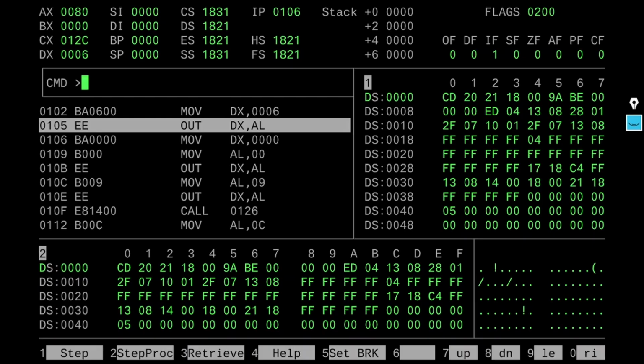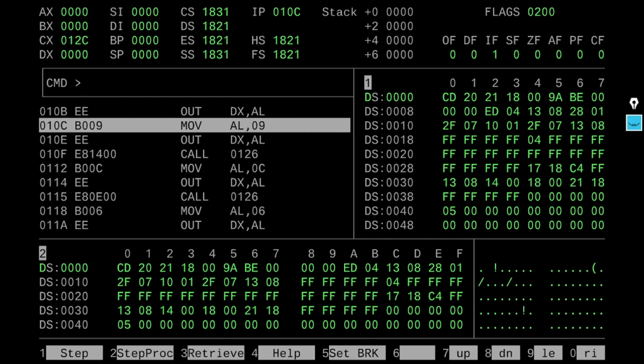That's the difference between the MOV and OUT commands in assembly language. I've executed this, and see, the value has changed here because I'm using the MOV command. And AL, I'm going to initialize to 00. All the values go out of the microprocessor 8086 via the DX port.